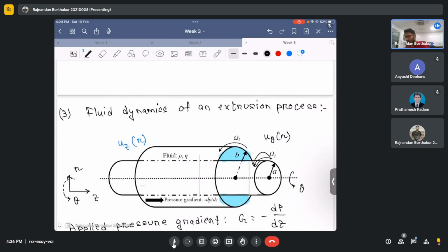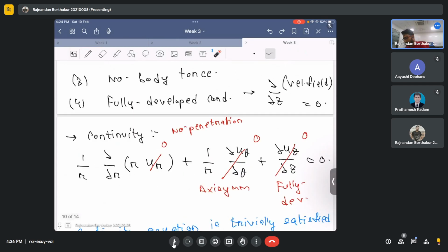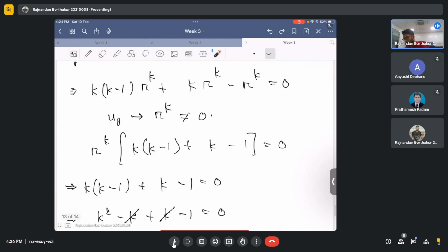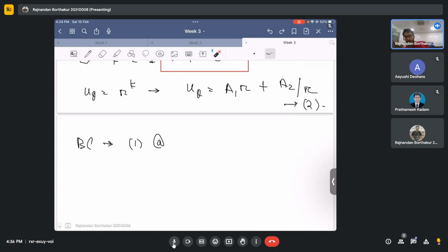See, the vorticity or the angular velocity. What is the direction of this angular velocity? If we apply the right hand thumb rule, it is in the z direction, and the radius is in the r direction, which means vectorially it becomes omega, the magnitude, into z, cross the r direction, which is r, and z cross r is theta, and that's why it's just omega times a. So I hope this is clear. I would write it down for you to be absolutely clear why it becomes just omega a.